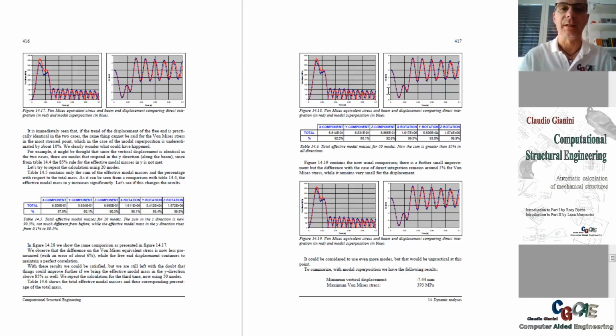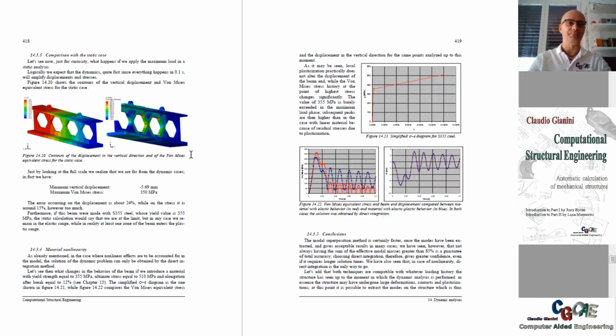Other comparisons are done, trying to match better by increasing the number of modes to be considered in the modal superposition approach. And finally, the difference between the two techniques ends when we have to enter nonlinearities, in the sense that the modal superposition technique can be used only for linear models, so no contacts, no big displacements, no material nonlinearities. If we have one of the three, then the only way to solve it is using the direct integration approach.